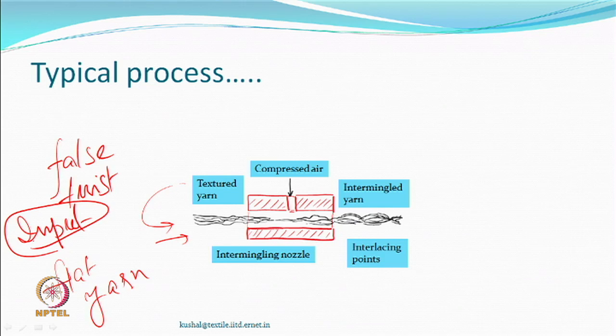Why not air jet? Because the air jet yarn is already entangled. It does not need any support. It is only such type of filament yarns where the filaments can get separated. Those type of yarns are the only ones which would require this additional pre-twisting before processing into a knitted or a woven material, or a flat yarn which is either textured or a flat yarn.